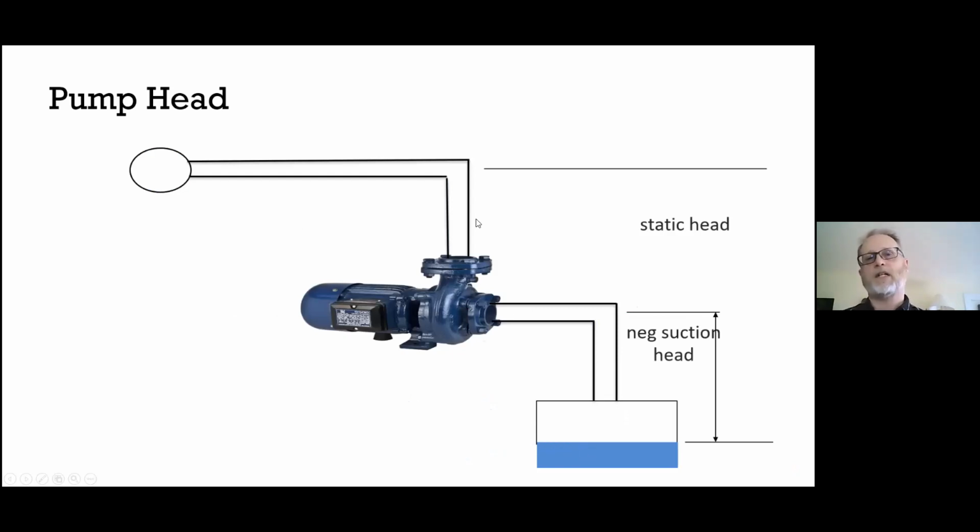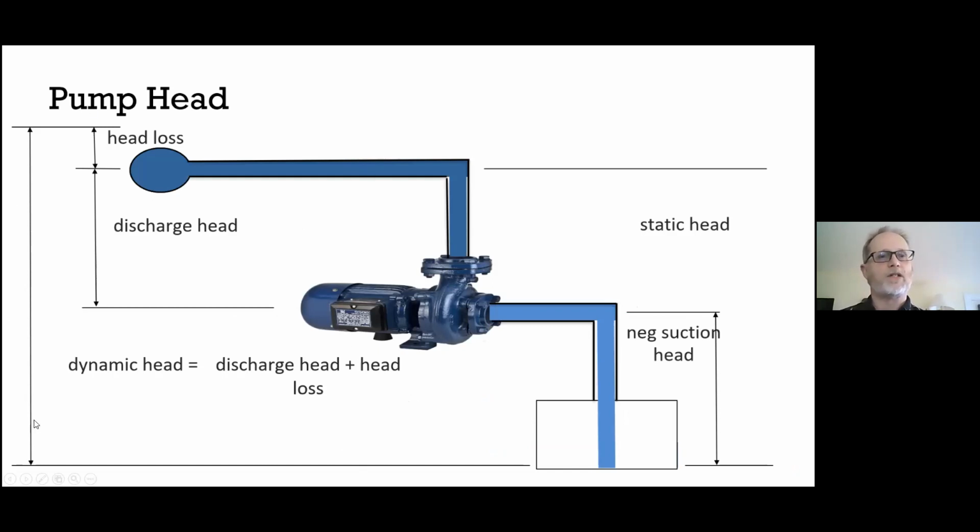Just because it's on the suction side of the pump doesn't really matter. We still have to lift water this entire distance. So there's our total pump requirement here. That's where knowing how your system is configured becomes really critical.